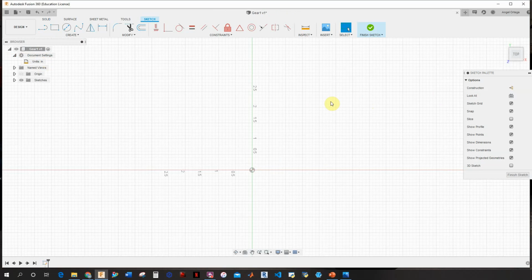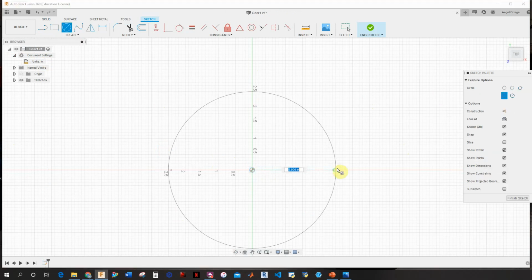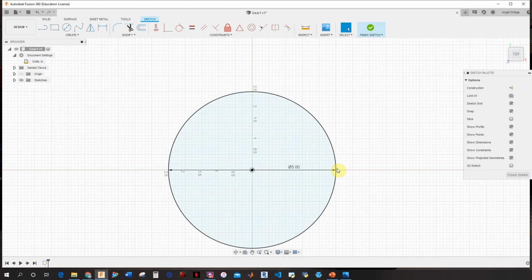Okay. So we're good. Now, for the picture that you saw previously, one of the biggest shapes there is a circle. So I'm going to take that circle, and if you go back to the image, you should be able to find the dimension, which is 5. So I'm going to make it a 5-inch circle. Now in this case, my circle is already black because it's fully defined.